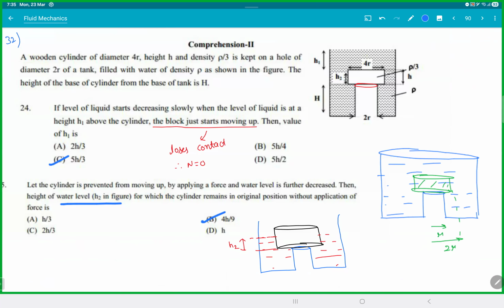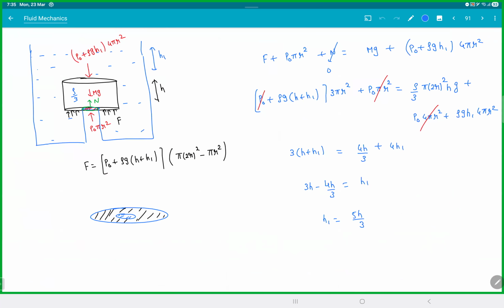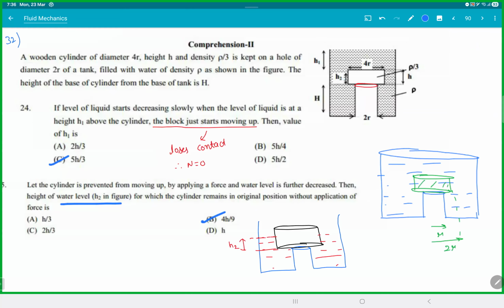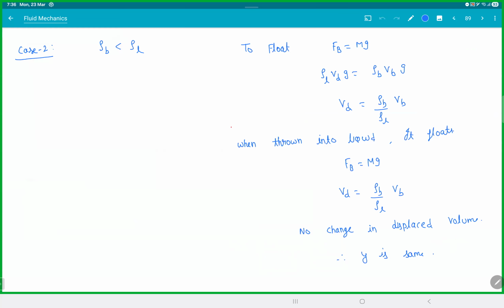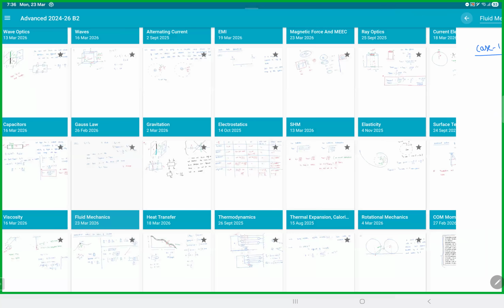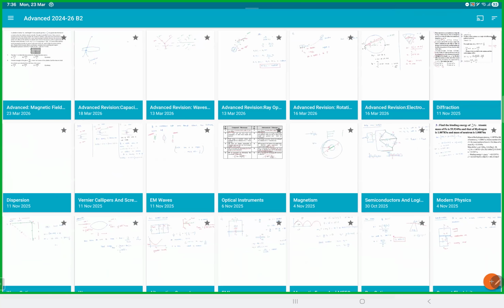If you look at the bottom surface here, look at the FBD here. The liquid is pushing and the atmosphere is also pushing. You cannot apply buoyant force in these kinds of cases. Clear with that? Just keep that in mind. If your entire lower surface is not covered in liquid, you cannot use buoyant force. Generally, these are the kinds of cases you will get. So in this case also, buoyant force is not applicable.